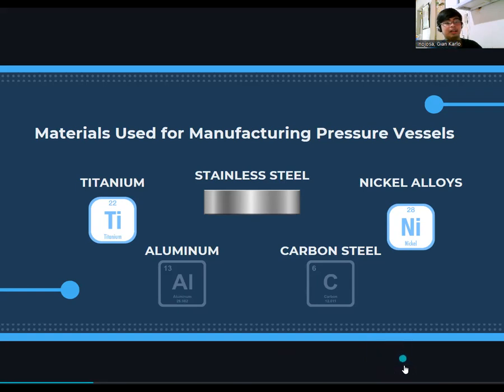It resists vibrations and shock and can be recycled easily. Last is the aluminum, which is capable of maintaining high tensile strength between 70 to 700 megapascal, and is easier and more cost-effective to machine compared to stainless steel, and has a larger coefficient of expansion compared to other metals.